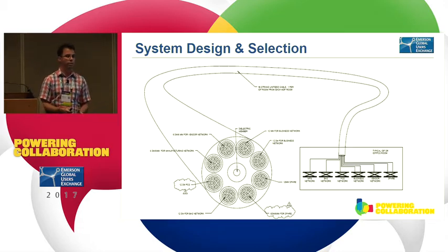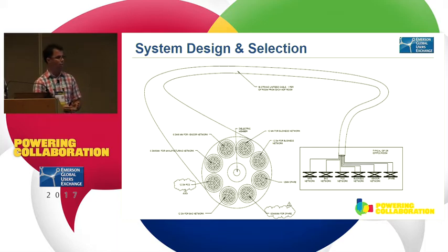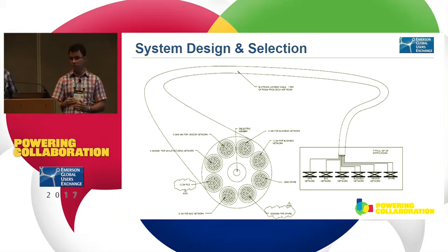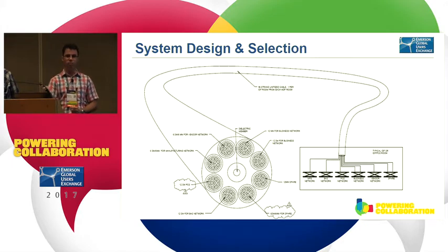We have 2 DeltaV systems. We have virtualization, which includes, in addition to having a primary and secondary network, the high availability or cluster management network. We have a dedicated batch executive redundant network, and all of those networks are going to be connected through this fiber optic strand from point E to point B.